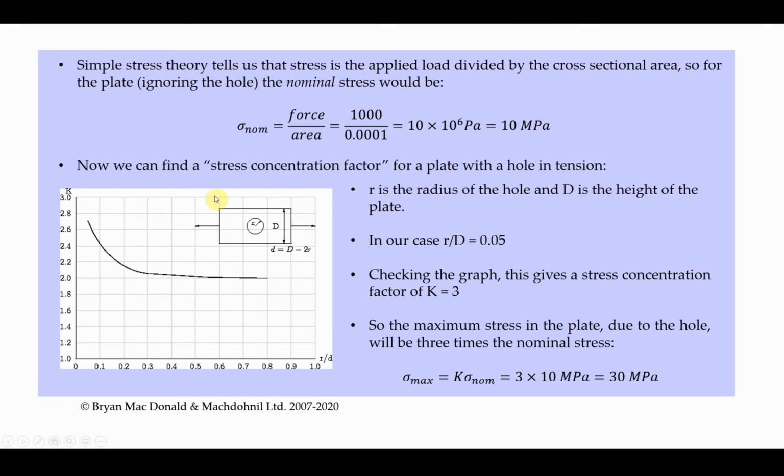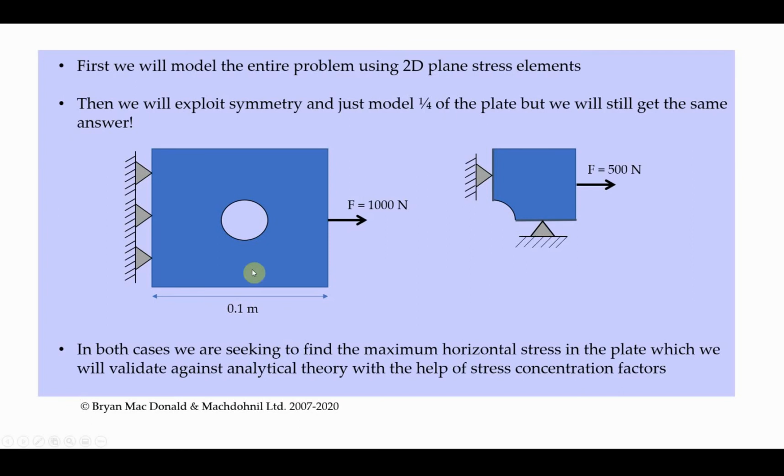Well, what about the hole? The hole obviously affects things. We know that the hole is a stress concentrator and it will raise the stress in the plate. If I just go back to the previous slide for 1 second, it's in this area here. If you think about this plate being pulled apart, this area here is going to experience the high stress. This is where it wants to tear apart, basically. If we were going to get a rip in the hole, it would occur here and here. So we're going to get high stresses in that area there.